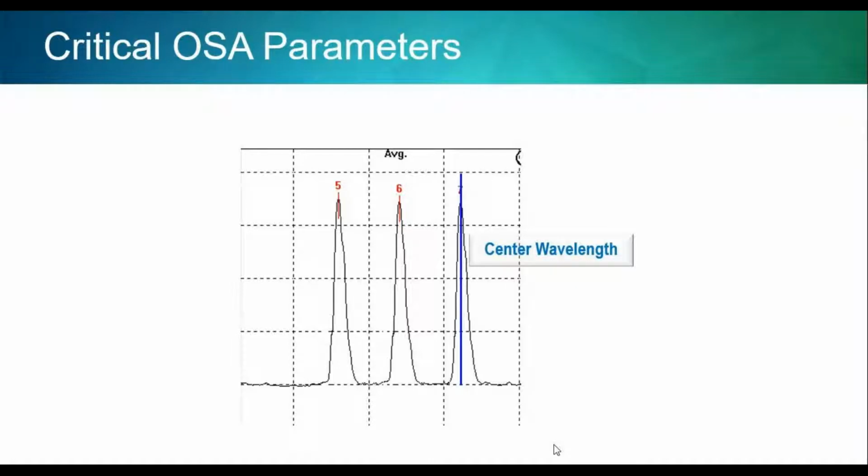It really requires a great accuracy to determine what the actual central wavelength is. And that's very important because you don't have that much leg room in terms of how much drift you can tolerate from the receiver end. Okay, so these values can actually be monitored, and you're doing provisioning. So you really need to make sure that you have an accurate measurement of the central wavelength.